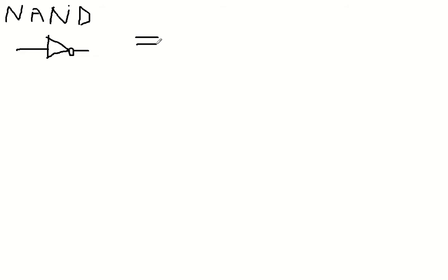Because if we look carefully, NAND gates have the symbol like this, basically, okay? So if you want to convert a NAND gate into a NOT gate, how is this possible? Because it has two inputs. So if you short these two inputs, now you can see it can be easily converted to a NOT inverter gate, isn't it? So I hope you are getting my point. This is the situation for NAND.